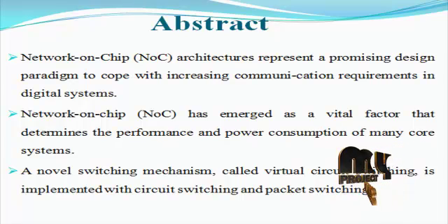In this paper, we present an improved design of the 2D mesh NoC topology which can reduce the hop count of long distance traffic. The basic concept of the design is the separation of long distance traffic from short distance traffic. We divide the mesh into several 4x4 meshes and connect the central nodes of each 4x4 mesh. Moreover, the central nodes of each 4x4 mesh are connected to the diagonal nodes.